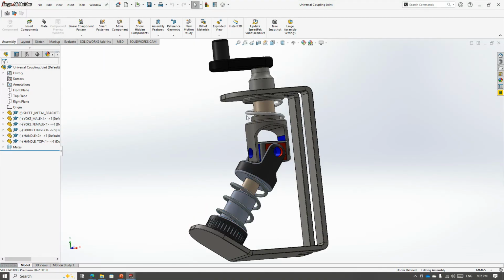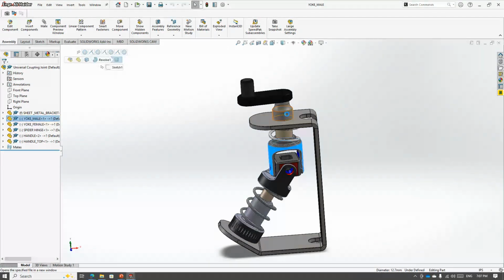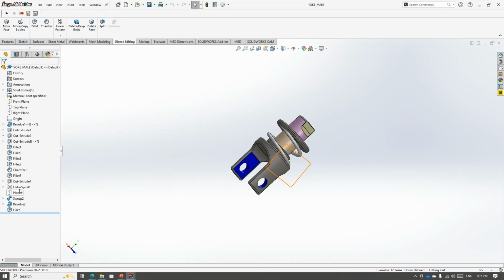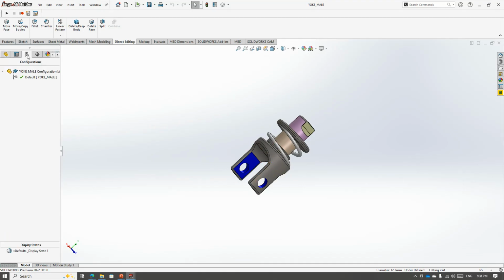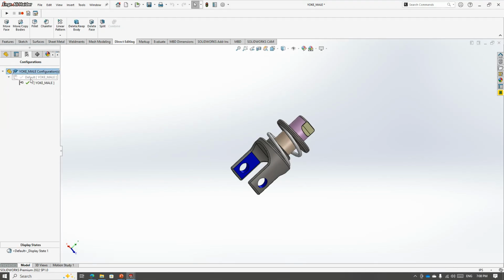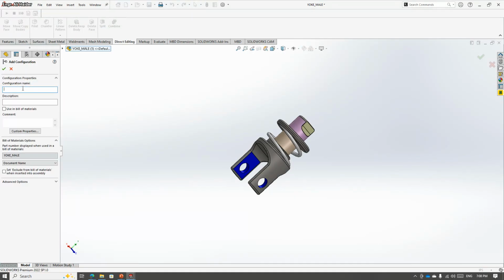So what you need to do is simply open the components that you want to modify one by one. First, I want to open this part, and then from the tree you will go into the configuration manager and right click on the default configuration and add a derived configuration from the default. This means you are going under this configuration. If I create one, you are going inside the main default configuration, and if you click here, you can create a new configuration. I will name it A1,